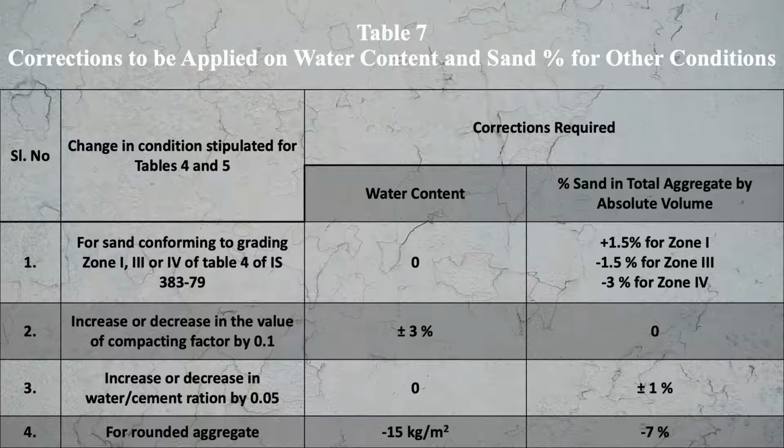So likewise, for different conditions you can read these values of correction in water content and correction in percentage sand in total aggregate by absolute volume, and these corrections will be used if conditions are differing.